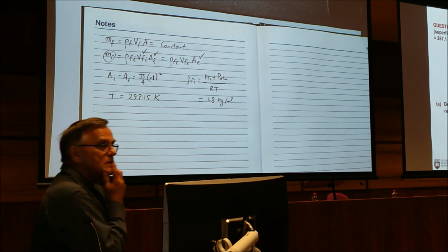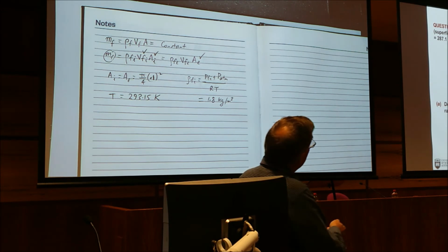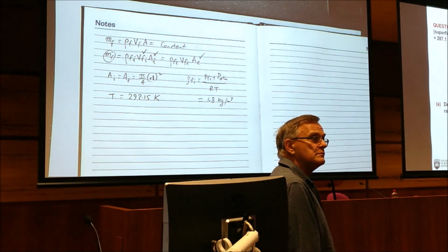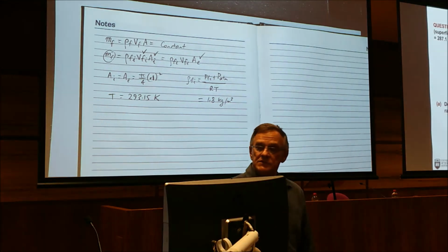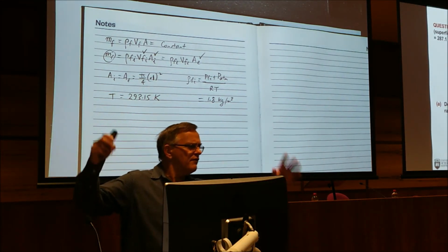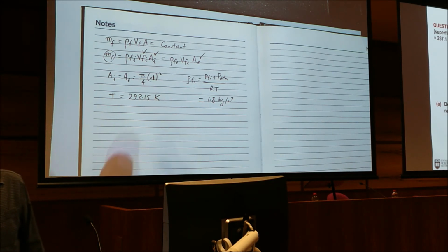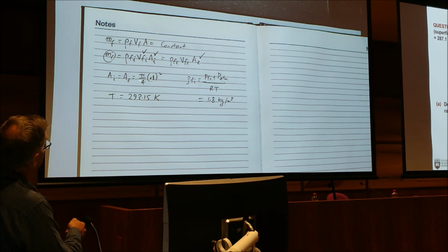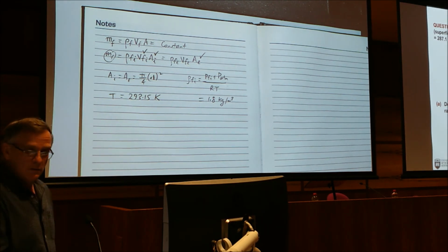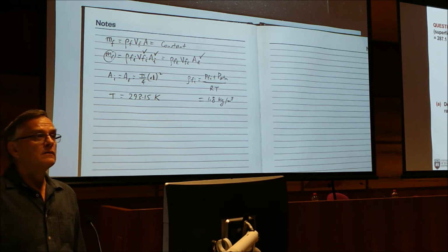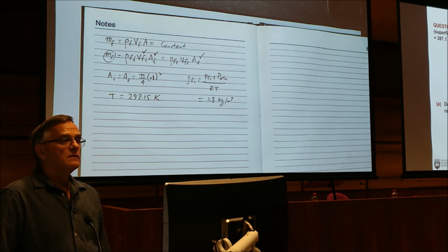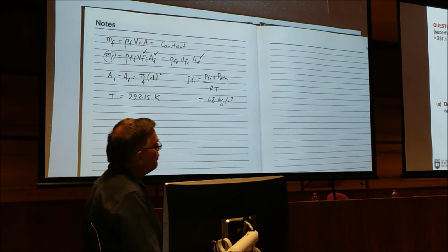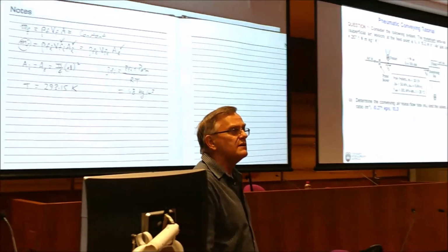So the gas density at the inlet of my pipeline is 1.8, the gas density at the exit is 1.2. It'll be 1.795, close enough to 1.8. So we know now what rho Fi is, times 19.2 times that will give you MF. So you'll get 0.271 kilograms per second in that calculation.